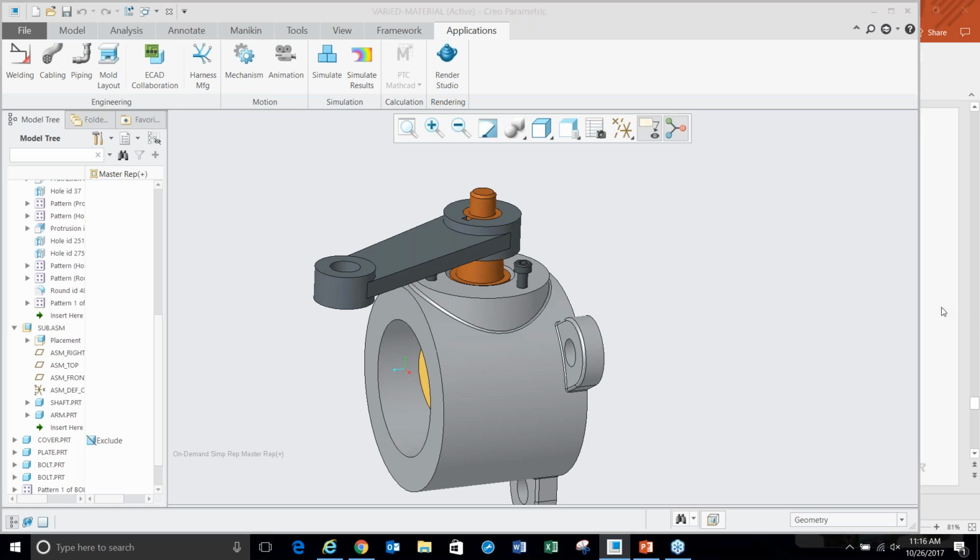Can appearances be used in drawing views? Great question. Absolutely. Using the all state. Remember, in the view manager, you have a combination state. So in the combination state, you should reference an appearance state, and the combination states can be shown in the drawing.